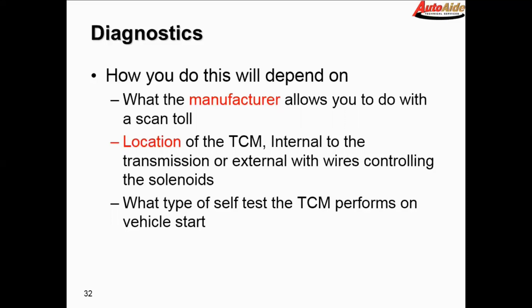Having said that, these solenoids are still powered through the bulkhead, and pretty much any transmission that I've ever worked on that had the transmission controller inside the box, you had pretty good bidirectional control with the scan tool, which means you can literally in the service bay get around the power wire that feeds the valve body and command the solenoids on and off and watch what they're doing on a scope.